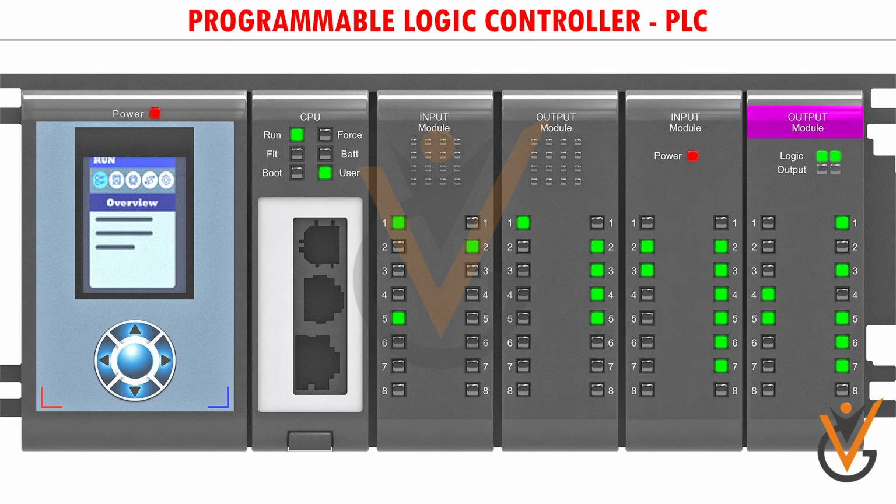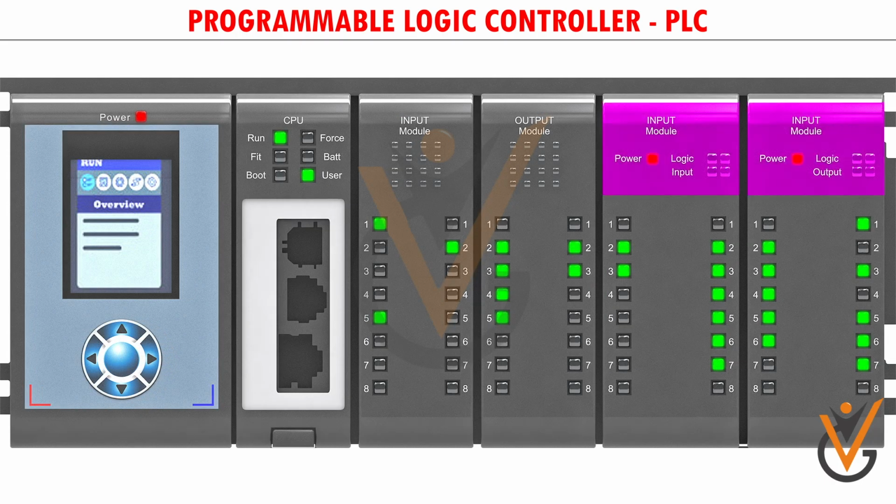The logic LED of the output module indicates that the output logic circuitry has received a command from the processor to turn on. As this power or logic LED alone cannot be used to detect malfunctions in the input or output module respectively, an additional diagnostic indicator is introduced by some PLC manufacturers. So, if both the LEDs are not on simultaneously, the malfunction in the corresponding input or output module can be detected.